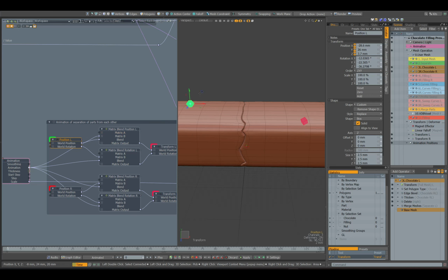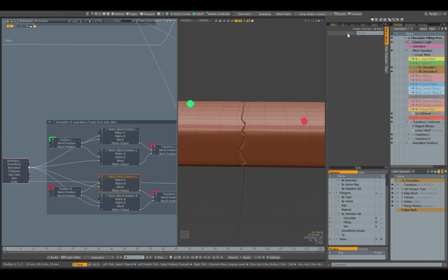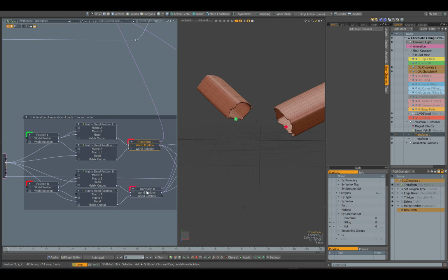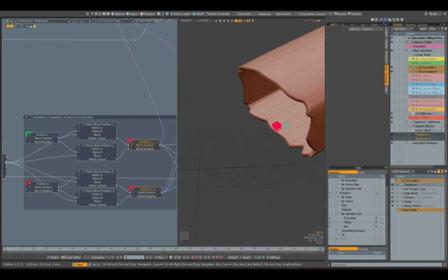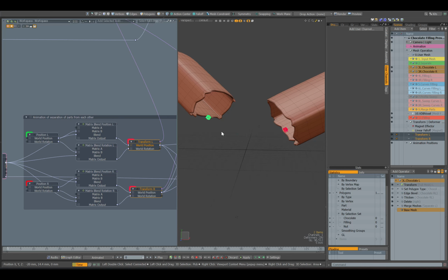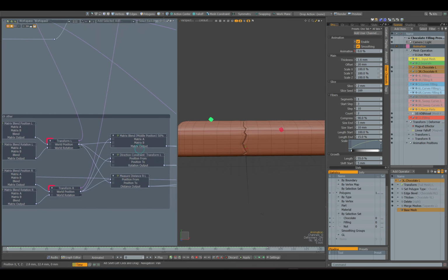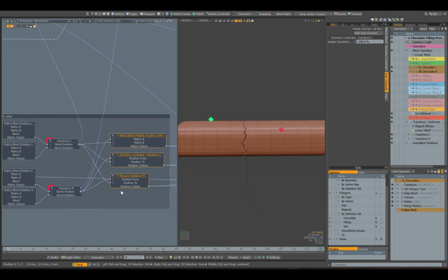You can adjust the position and rotation of the locator to get the end position of the animation. I did the same for the rotation. Matrix blend allows us to gradually switch from one position to another. I connected the animation channel to the blend channel so we can animate the locator positions. Then I connected the output channel of the matrix blend node to the transform deformer locator. In this way, I animated the position from 0 coordinates to the positions of the colored locators. What I used the following three nodes for, I'll explain a little later.